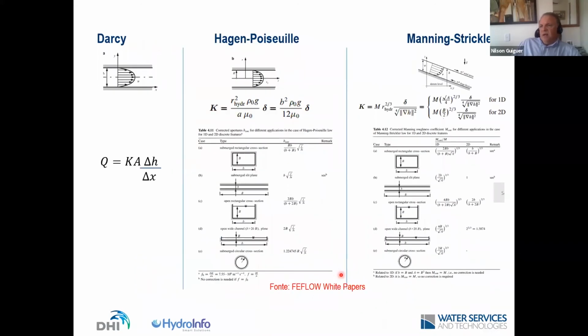In these individual elements, in any element basically, you can have Darcy's law, so flux is proportional to gradients, and there is one constant K value. That one you can use inside a line element as well, because you can still say in this line element it's proportional, and I assume one constant parameter called K that may be, for example, higher or maybe lower than your porous medium. So once the water hits there, it meets that higher K and deviates to that, but inside that plane only.